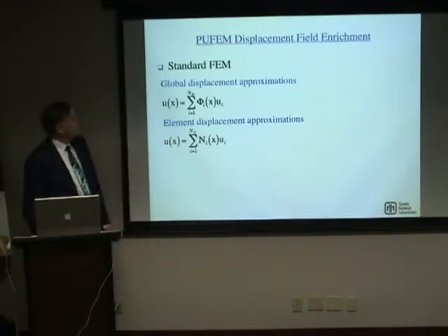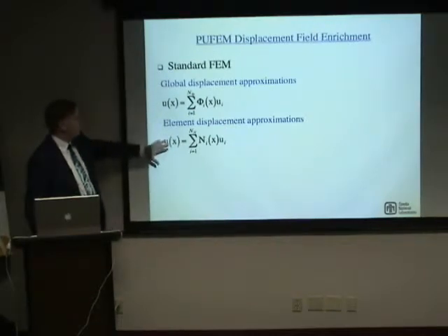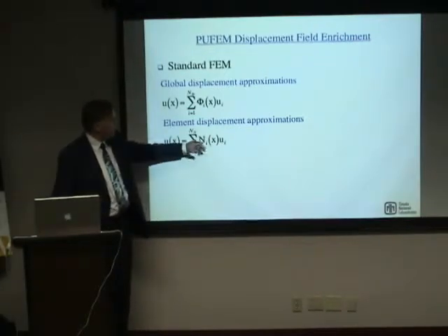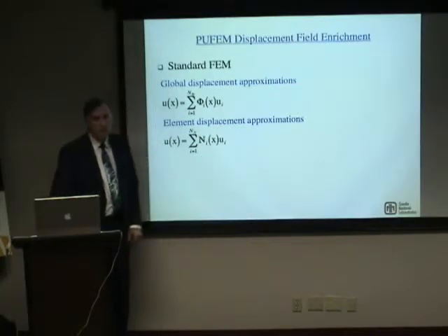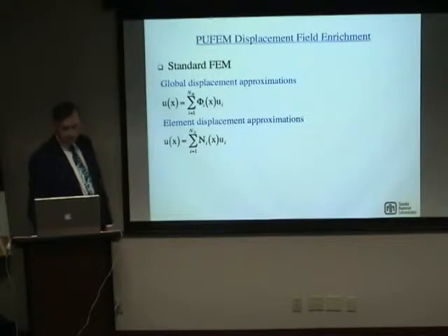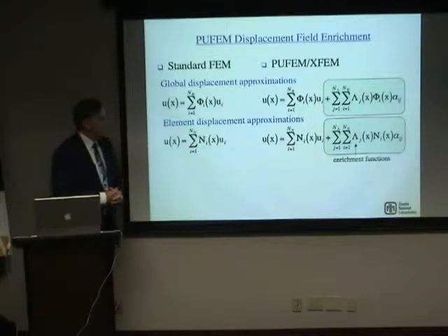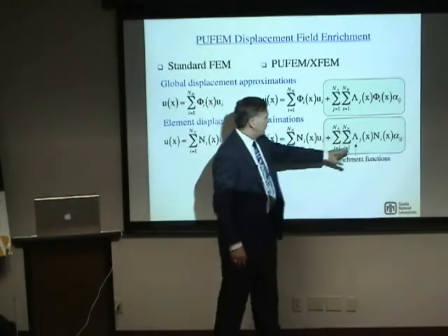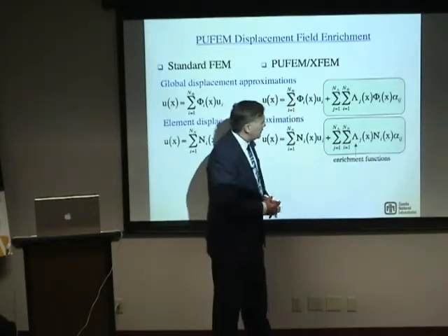So I've been using the term enriched methods. Let me start off. We can either look at this at a global or an element level, but let me just use element as an example. So our displacement field in a typical or standard finite element method is one of having these shape functions, typically obtained as polynomials, multiplied by the corresponding nodal displacements, okay? And in PUFEM or XFEM type methods, the extension that we make here is that in addition to these terms, we add in some terms where we have these enrichment functions multiplied by shape functions.